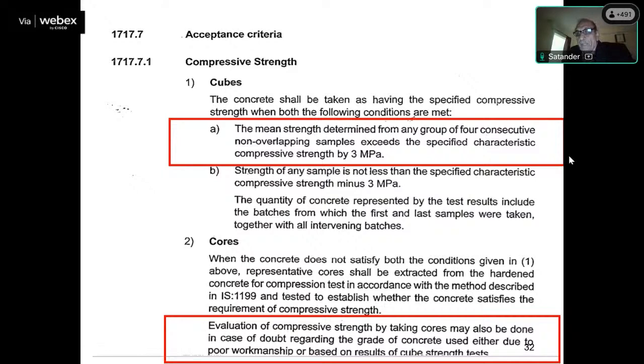I am showing you this rebound hammer, or everyone might have this also. With the rebound hammer, you can find out roughly the strength. Suppose you find it is giving a very low value, 20 or so, then we can ask to cut a core from here. Suppose he asks you to come and cite at so much and he did the work, then it is your duty to check the core also, or do an NDT test or other test. Correct? So this is the reason.